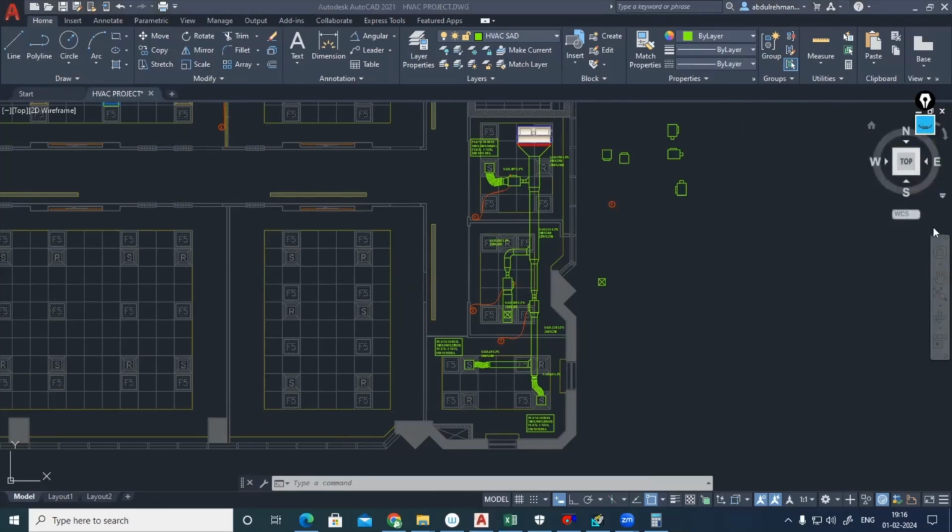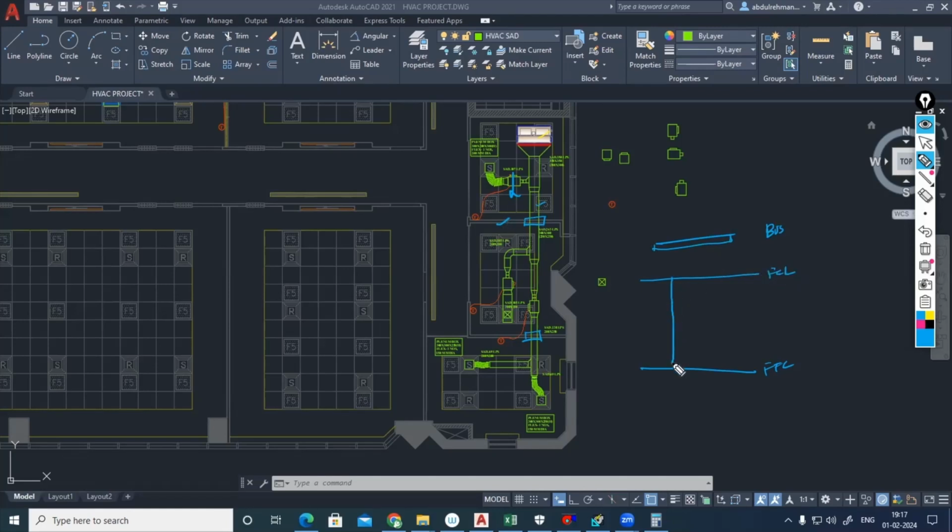See here, you can see the machine is located there only, here. And it is delivering to the front area, right? But you can imagine this supplier duct has to cross this wall. Suppose if this is your finished floor level, and that is your bottom of slab, and if this is your false ceiling level. If this partition wall is extending only until the false ceiling level, then no problem. You don't want to make any hole in this partition wall because it's a common. Even return is also common there.